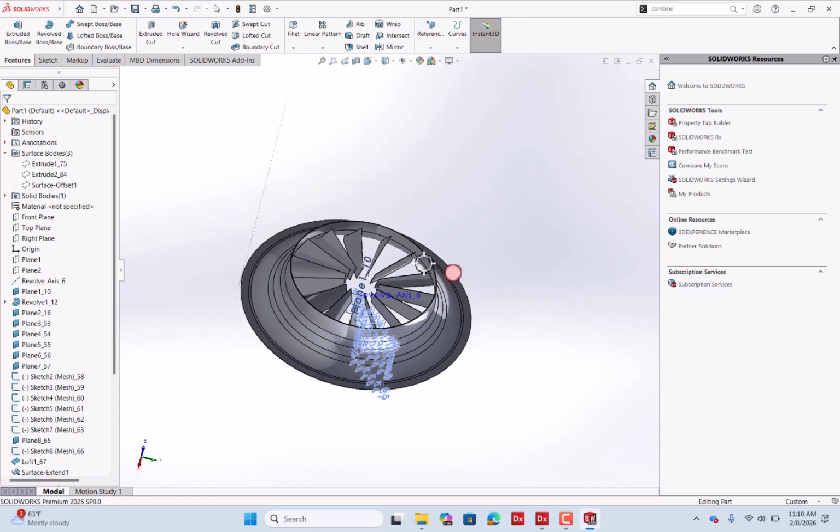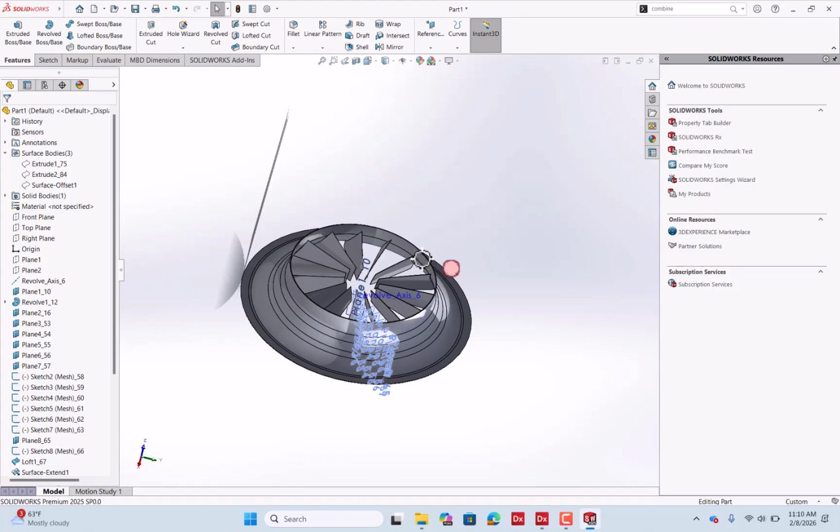Even though it needed surfaces, we were able to extract the surfaces that we need, followed by performing just the extending and trimming process in SolidWorks. This is how we can extract lofted surfaces in Geomagic Design X Go and use it for completing the model with a very few minor steps in the CAD atmosphere.